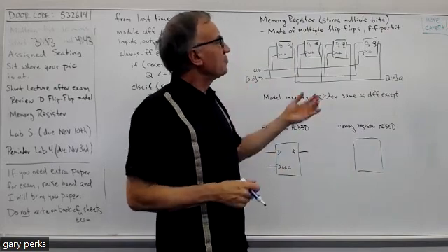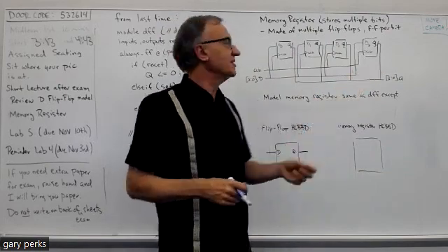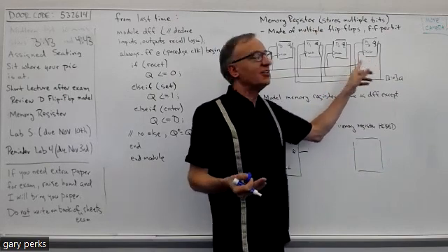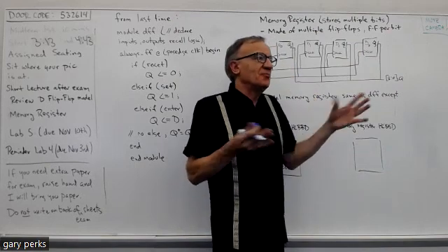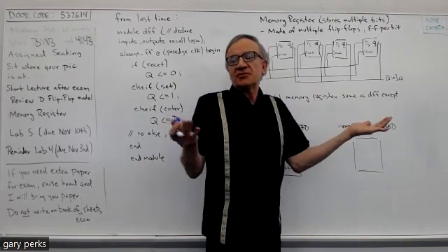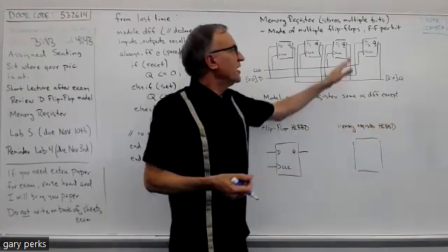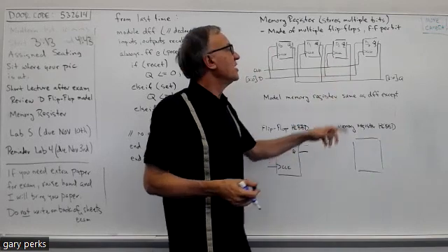Now, what's different with the register compared to the adding circuit you did previously is that the register, because it's sequential, has a clock input, right? Your adder, your RCA, had no clock input because it wasn't sequential, it's combinational. There's no storage in an adder. So anytime you have a sequential type of circuit, it's going to have a clock input.